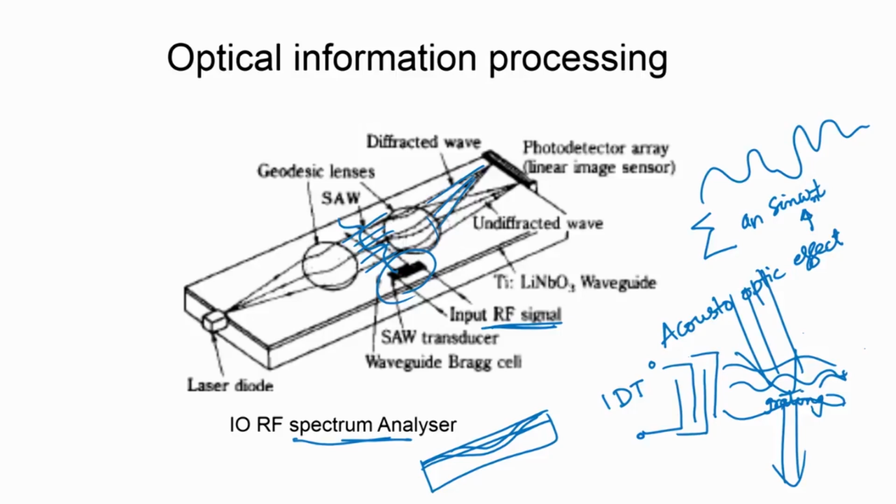the overall grating. So, we can expect that we can calibrate the output and work out that the deflected signals at each of these photodetector arrays can correspond to different components of the RF signal. So, if you have an RF signal something like this, you can expect and calibrate the output current of the photodetectors in a similar fashion, and we can use it for RF signal analysis.